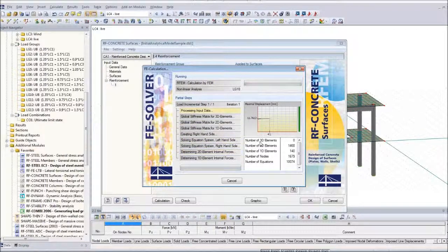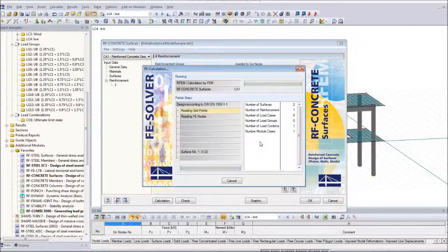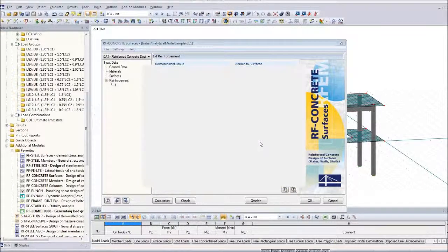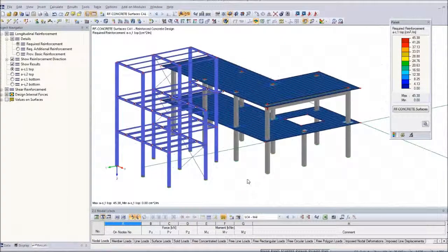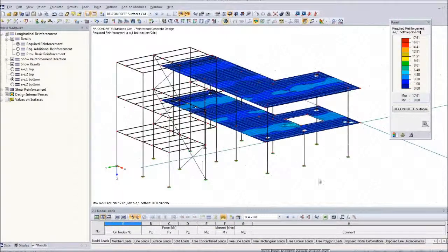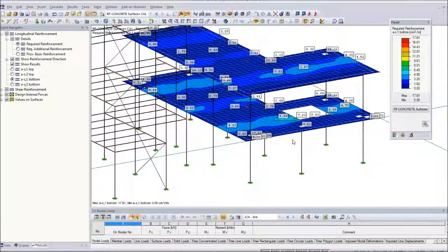And what we can do with the reinforcement, we cannot export it to tekla at the moment directly. We can reference, for example, a DXF file that we can export from RFEM. We have some companies now that start to do their own implementations. It means that we have the COM application also for reinforcement information, and we can get all these reinforcement values to tekla, and tekla has then the option also with the COM interface to create rebars, real rebars, not only theoretical reinforcement content, but also rebars from our results.